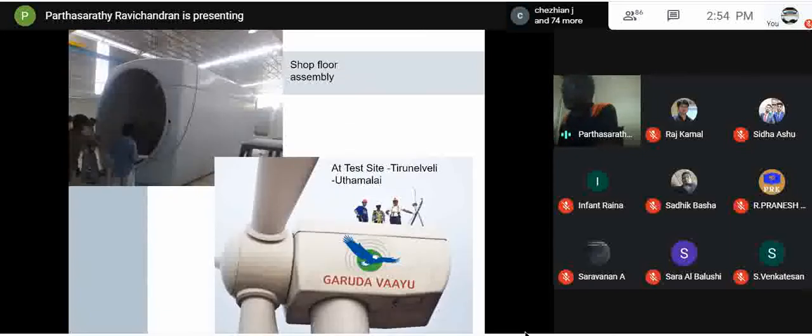So this is the actual picture, just before the dispatch. We have to see that it is all properly aligned and bolted up, and then this is how it is sent. This looked pretty plain before the sticker was on. On the right-hand side is how the sticker looks. This was at an actual site, the same nacelle cover, with 3 technicians standing on top, and still safe. There was no problem. We were able to recover, improve the design defect, and assure them that when you are on top, this cover will not give way.